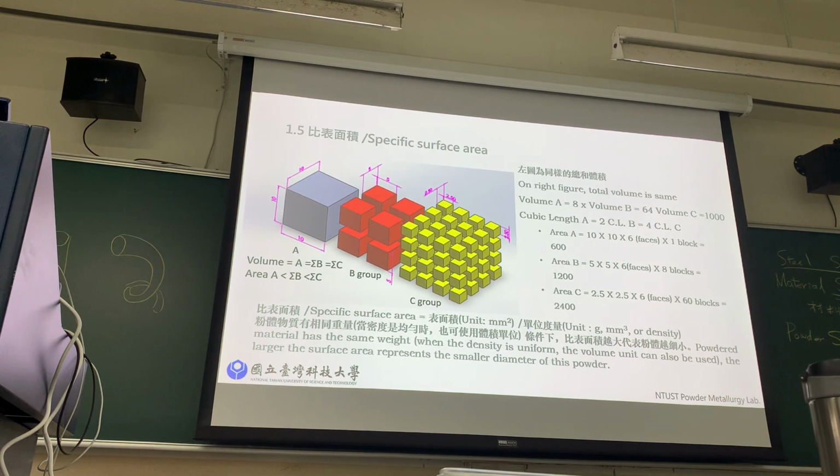But with many balls, every powder particle will be heating itself. Everybody heating, so the powder temperature will be higher, and the process temperature should be higher. If the temperature goes over the melting point of the powder, your process is not particle forming, it's liquid phase forming, which is different. So you should remember this one.